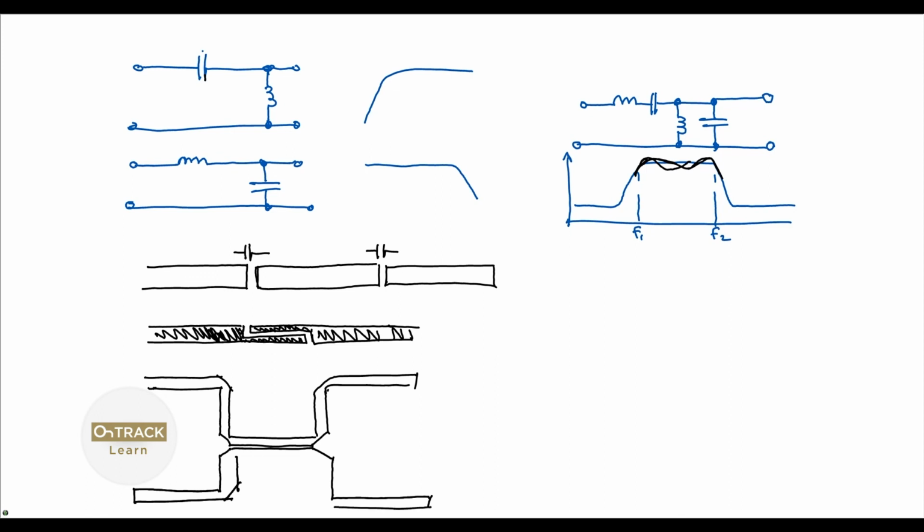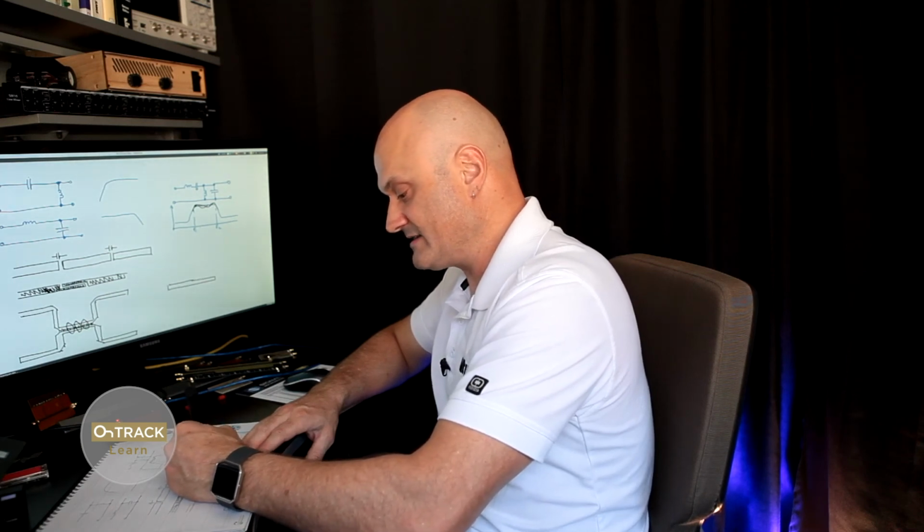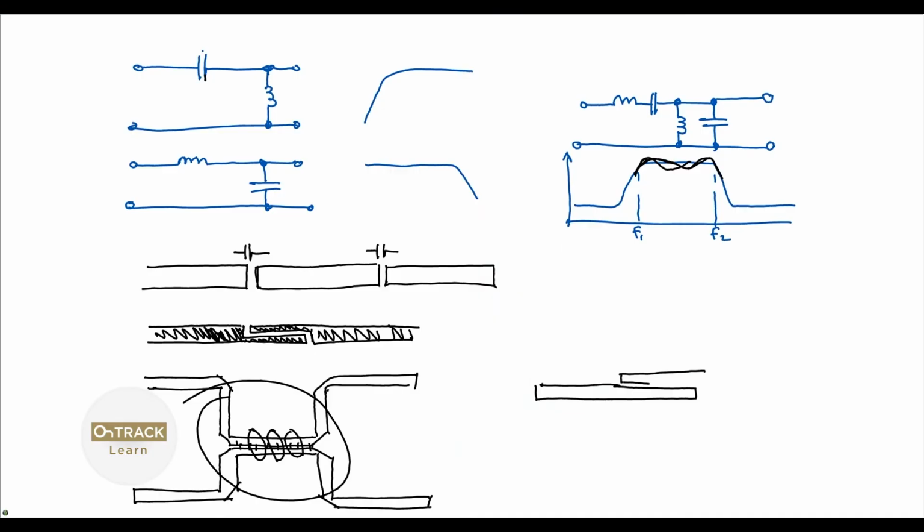All right. And we're coupling signals here. We have capacitive coupling and magnetic coupling here. So we can actually make use of this. This has a certain bandpass frequency response, and it's a very useful way of also constructing filters. So we could actually have a transmission line coming in, and instead of having the directional coupler look like this, we can place it with a quarter wavelength overlap, or some multiple thereof that suits our needs.